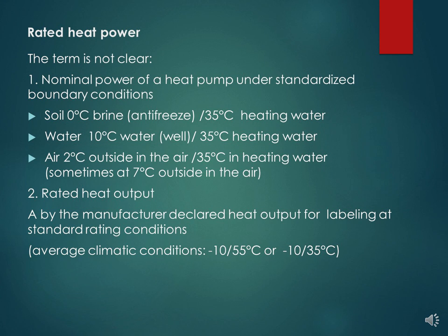Second, the rated heat output, which is the manufacturer's declared heat output for labeling at standard rating conditions. This applies to the average climatic conditions of -10 degrees Celsius outside and either 55 or 35 degrees Celsius in the heating water.